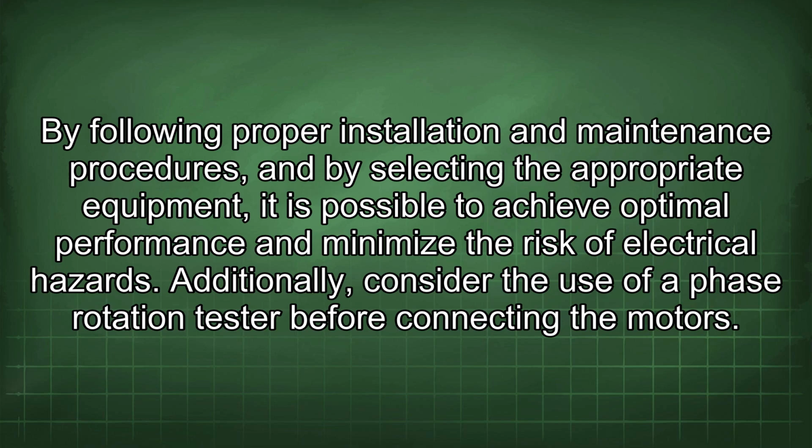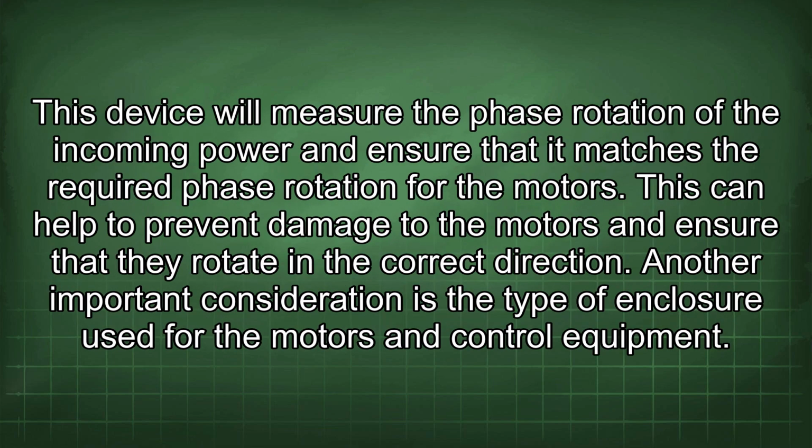Additionally, consider the use of a phase rotation tester before connecting the motors. This device will measure the phase rotation of the incoming power and ensure that it matches the required phase rotation for the motors. This can help to prevent damage to the motors and ensure that they rotate in the correct direction.